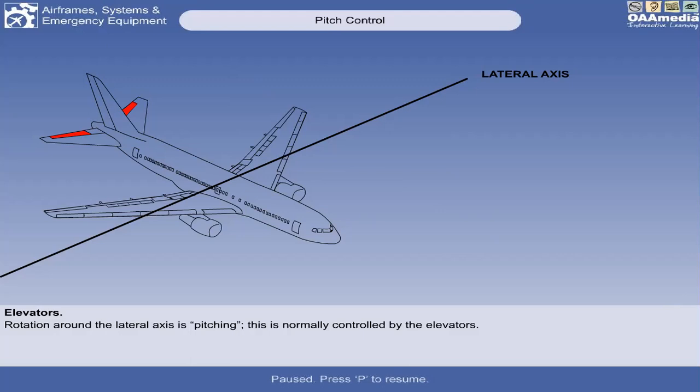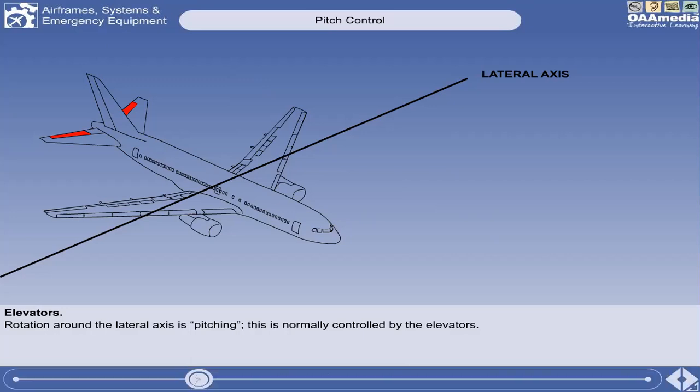Ideally, if you're going to design an aircraft, the center of gravity must be located within portions of the chord of the wing root. Within those parameters is where the range of the CG, or the CG limits, usually lie on the airplane. It is expressed in terms of the percentage of the chord of the wing. So, we'll continue with pitch control, and to give an adequate rate of pitch for maneuvers.